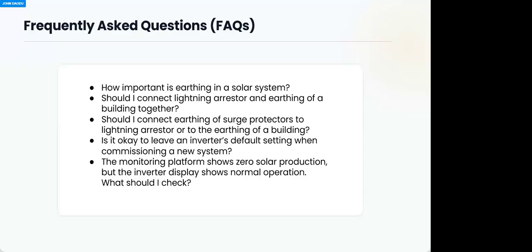And then it depends on what you want or what the client wants. For instance, the client wants that when the battery goes down to almost 20%, that's when the grid should be acceptable. These hybrid inverters today have all these functions. So it is your own remit to check which setting is going to do this, so that the client can use more of the battery and more of the solar, until the battery goes down to that 20%, and that is when it's going to accept grid. That reduces the cost of energy from the public source, because that's what many people want to cut off.